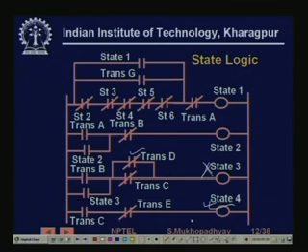So you see that mechanically, once we have developed the state graph, we can simply describe its behavior mechanically. Corresponding to every transition we are going to have one rung, corresponding to every state we are going to have one rung, and as I have described, we are going to put the enabling logics.